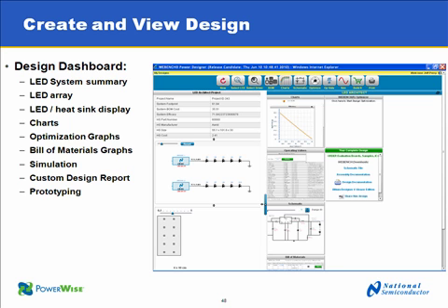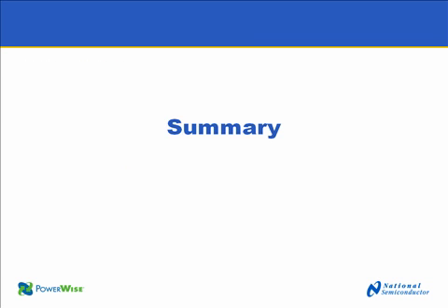Above that, you've got the LED block diagram. And then finally above that, you've got the system level parameters that we talked about, the system footprint, system BOM cost, and system efficacy, and also your heatsink parameters. At this point, you can fine-tune your design. You can go in and do component changes and optimize it even further. And then you've got your LED and driver design.